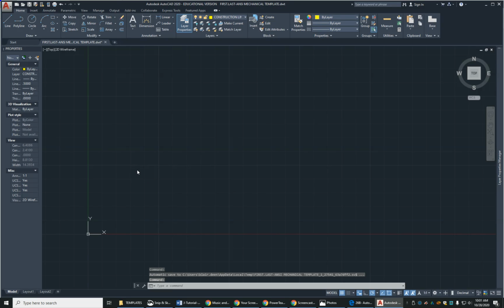So make sure those get turned back on for right now. So XL, enter. All right, and I'm going to start at the origin. So I'm going to do 0, tab 0. XL, enter, is for construction line. And then in my cursor, I'm specifying the specific point of exactly at the origin.